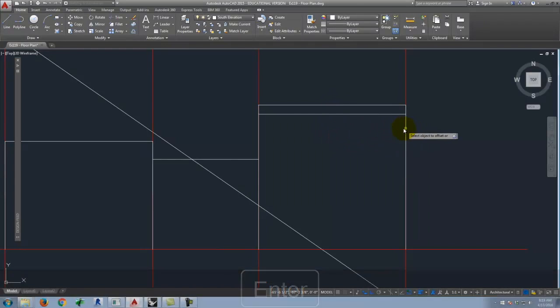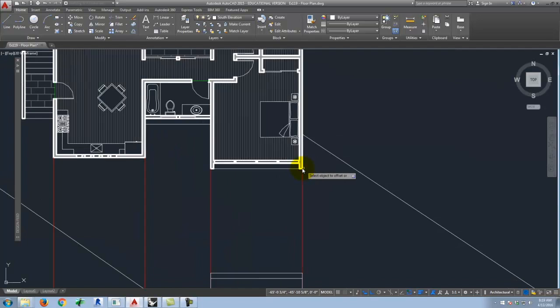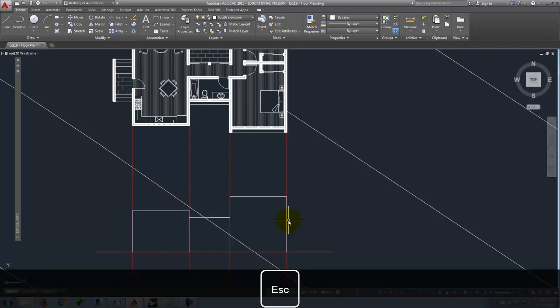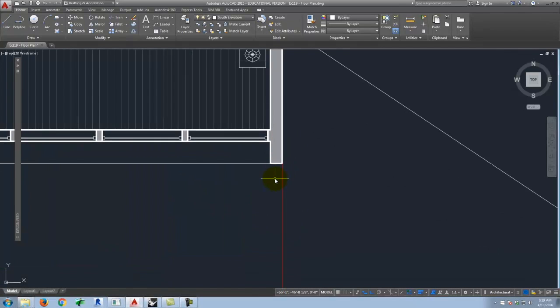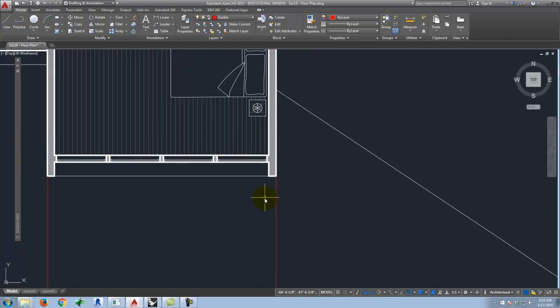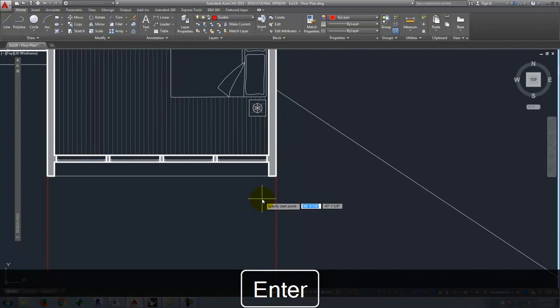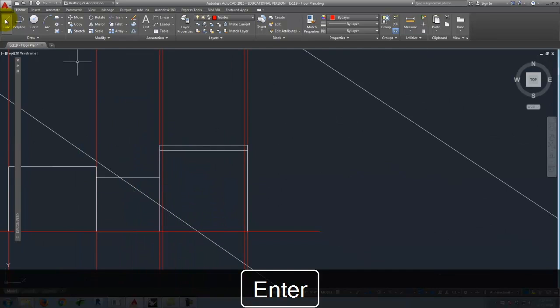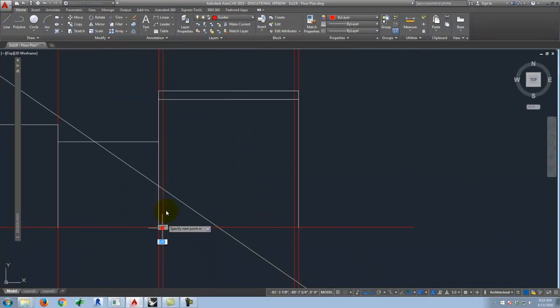right there. And then each of these walls is 6 inches thick. So I have two ways of doing this. I could offset this side, or I could do another guideline that is a ray. So let me go back to guides. And I could say ray from there down, and from there down. And I could use those to then draw this part of my wall.